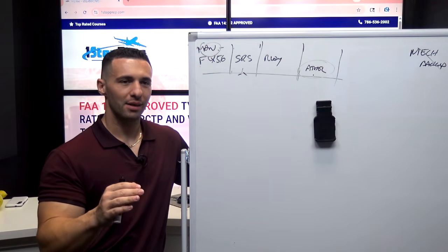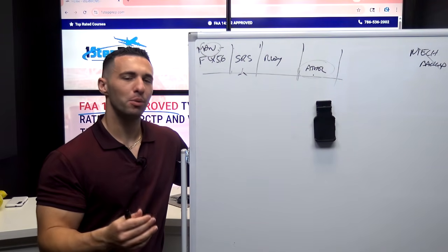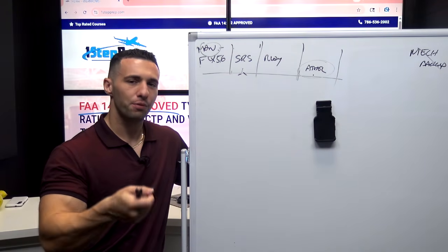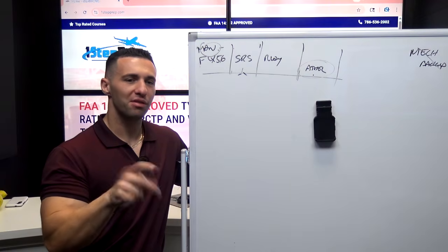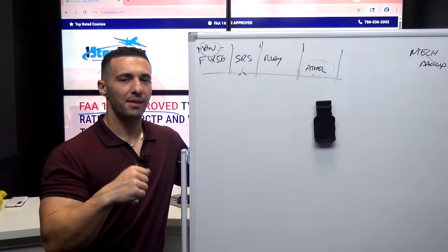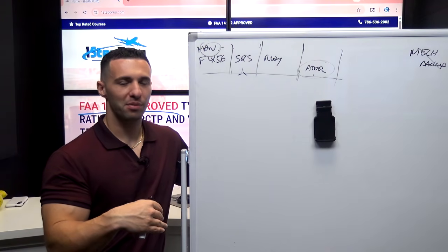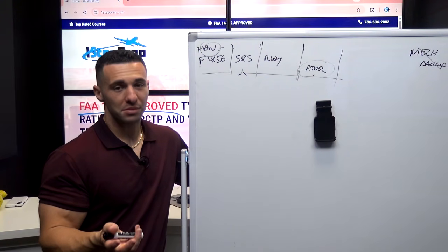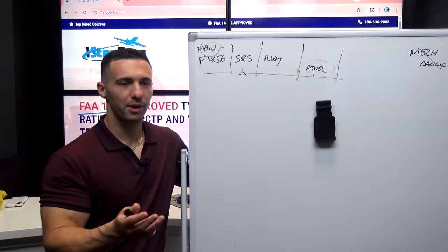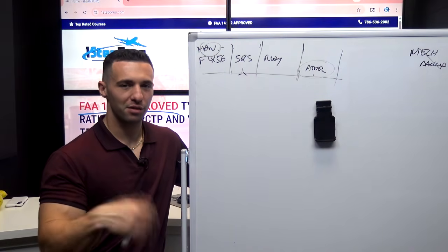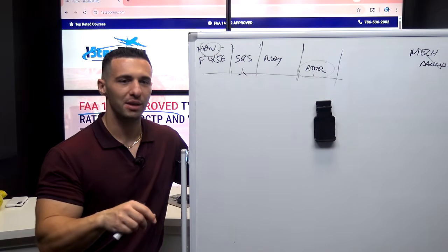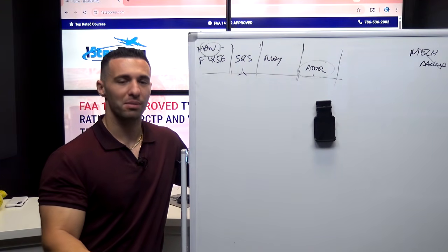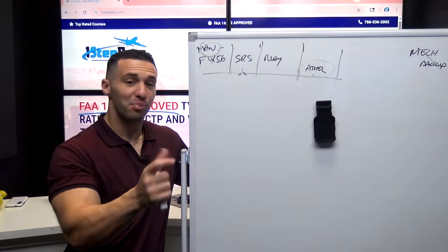This is another thing. A lot of times I see people configuring, first they get to green dot, that's fine. Then they throw flaps 1, but then they don't slow. And then they just maintain the green dot speed with flaps 1. That's not very fuel efficient, so I don't really recommend doing that. If you're going to fly green dot, just fly green dot. And then when you start slowing, throw flaps 1, go down to S speed. If they give you a reduced speed of 170, you go flaps 1, and then S speed is pretty much in the vicinity.